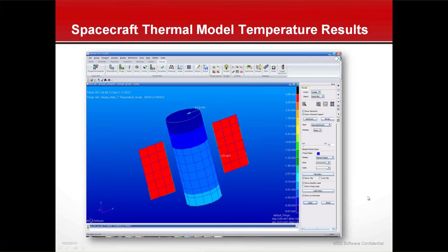And then when you close Thermica, after you've computed your orbital heating parameters and your view factors, we fold all that data back into our Patran model, and we calculate our temperatures based on this Patran model and the conduction here and all the thermal features you've added in Patran, and now you have nodal temperatures, the temperatures at each node in this model, and this could be used for thermal stress in Nastran or thermal distortion calculations, like on a mirror or an optical payload.